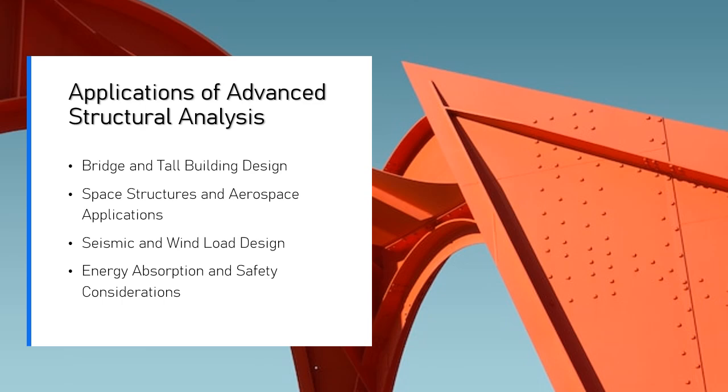Advanced design. To reduce the effects of seismic shaking, engineers incorporate energy dissipation systems such as viscous dampers, tuned mass dampers, and friction dampers. These devices absorb a significant portion of the seismic energy, preventing the structural elements from experiencing excessive deformation.